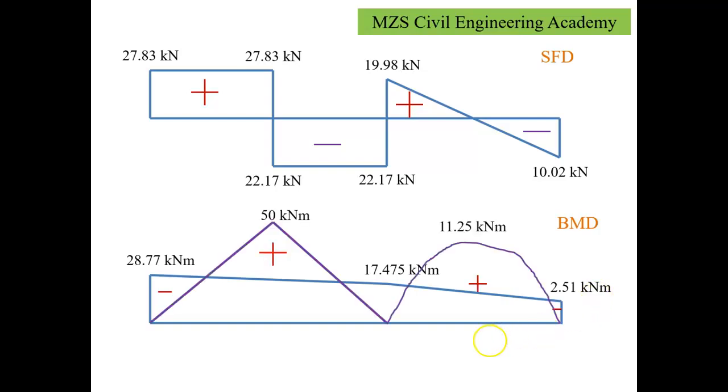If you overlap the free end moment diagram with this fixed end moment diagram, we get an envelope, which is said to be an integrated envelope or balance envelope with reference to the free end moment and the fixed end moment. This balance envelope, which is given in the sign minus plus, will be called the net bending moment.